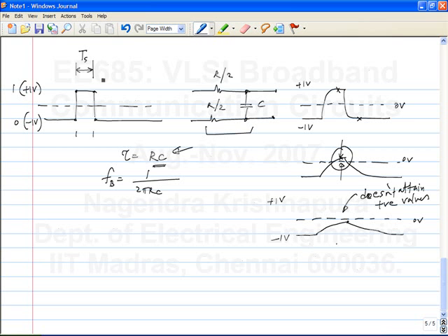And this is the kind of case that you encounter normally, let's say in the lab, when you connect a pair of wires to take signals from the signal generator to the output, you don't think of all these impairments, right? That is simply because the time constant in that case is much smaller than the time period that you are interested in. Okay, but you will see cases where the time constant is comparable to or much larger than the time period that you are interested in. And that is true for the cases that we saw earlier.